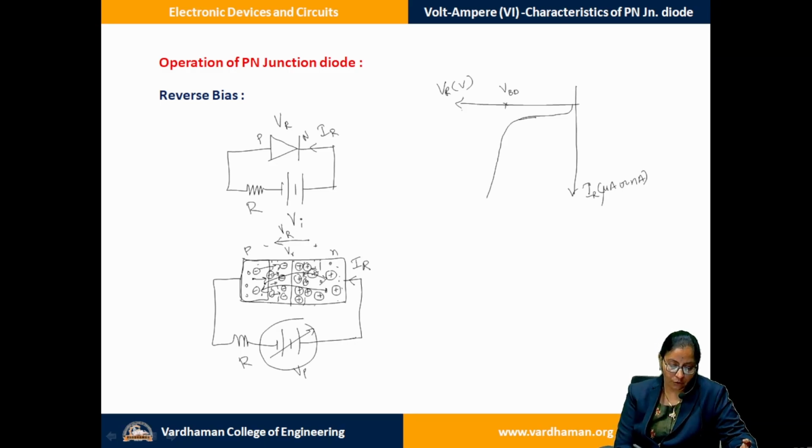At one particular point there is always a threshold for everything. Till a certain value, as we increase the reverse voltage, the current increases slightly. But when the kinetic energy goes beyond the barrier potential, the particle concentration increases because of the avalanche breakdown, and avalanche breakdown is because of avalanche multiplication.